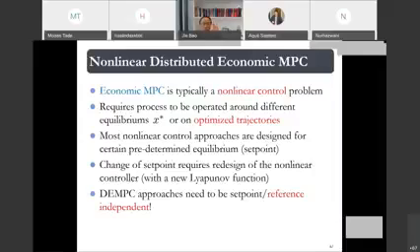So fundamentally, it's a nonlinear control problem, but it's actually more complicated than a normal nonlinear control problem, because a normal nonlinear control problem assumes that we are doing the control design for a given equilibrium point. So if we design a Lyapunov function, it is designed for that particular equilibrium point, and the control design would ensure stability around it and drive the process to that equilibrium point.